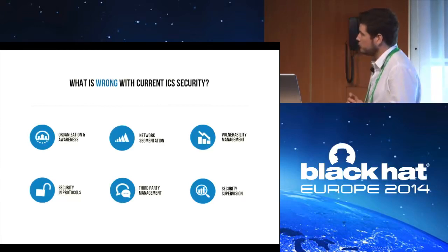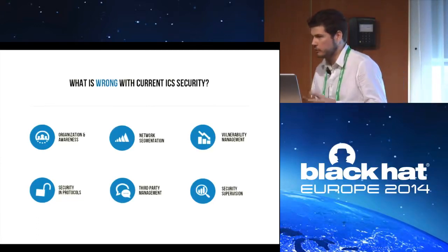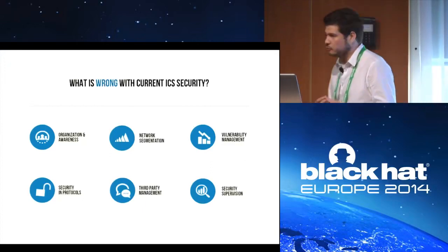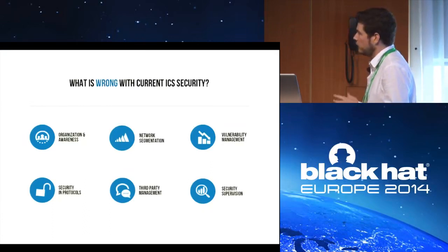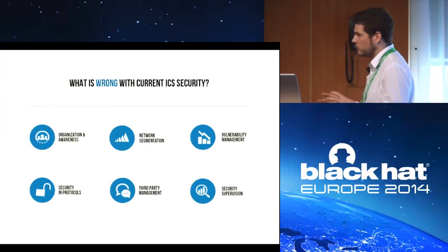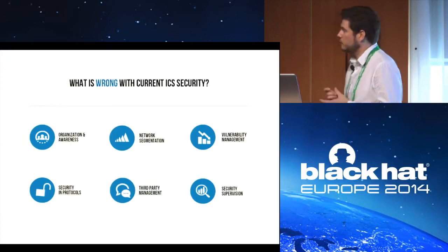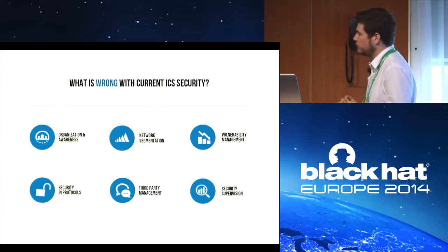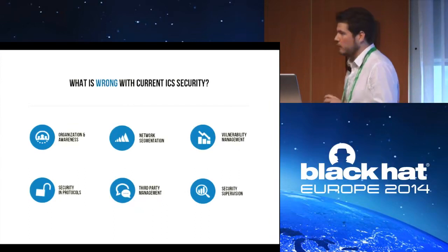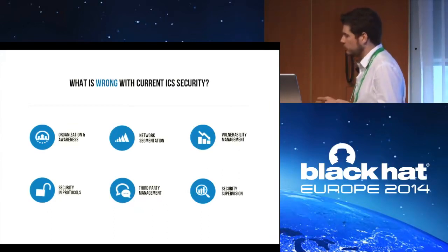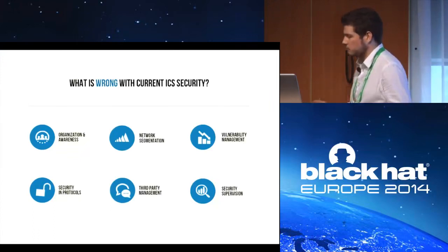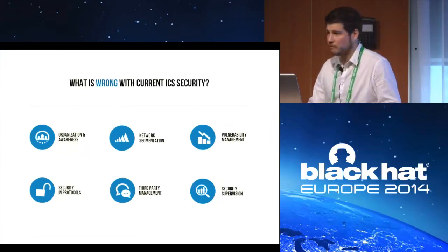The next topic is security supervision, which is a hot topic in the corporate network. Most of the time, people try not to focus only on protection, but also on the ability of detecting any security breach and responding to it. Funny thing is that ICS and SCADA is all about monitoring, but it's monitoring a process, which is quite different from monitoring the security of a process. So the logging capabilities of the PLCs and other devices are most of the time quite low. And at the moment, I've never seen someone performing a real syslog on ICS and correlating the logs. Maybe in a few years we can see that, but at the moment I've never seen it.